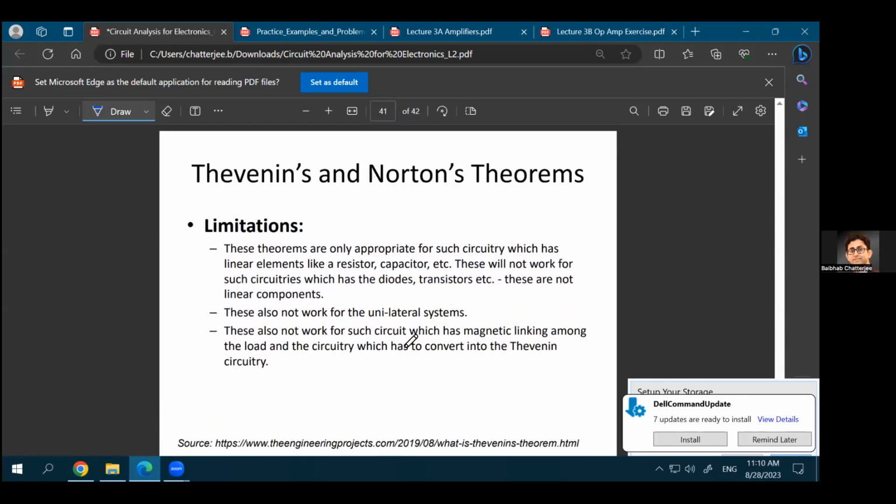So that's the example of Thevenin's theorem. I think you already know about Norton's theorem as well from your 31111. But the Norton theorem is just the dual of your Thevenin. There, instead of modeling the black box using a voltage source and a series resistance, you'll model the black box using a current source and a parallel resistance.